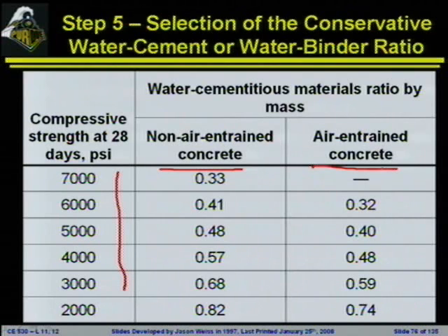What's the shape of a capillary pore? Could be tortuous, could look like a monkey, could look like anything, right? Doesn't have a particular shape. What's the shape of... I got somebody confused. They're looking for the monkey inside of the concrete. All right. Don't disregard. It could have an irregular shape. Let's go back to irregular shape. It's not monkey shaped. I don't want to see that on an exam. So our capillaries are irregularly shaped because they're leftover space from when the irregular cement particles start hydrating. Our entrained air is what type of shape? It's going to be spherical. So it's going to be a very well-defined shape inside of our system.